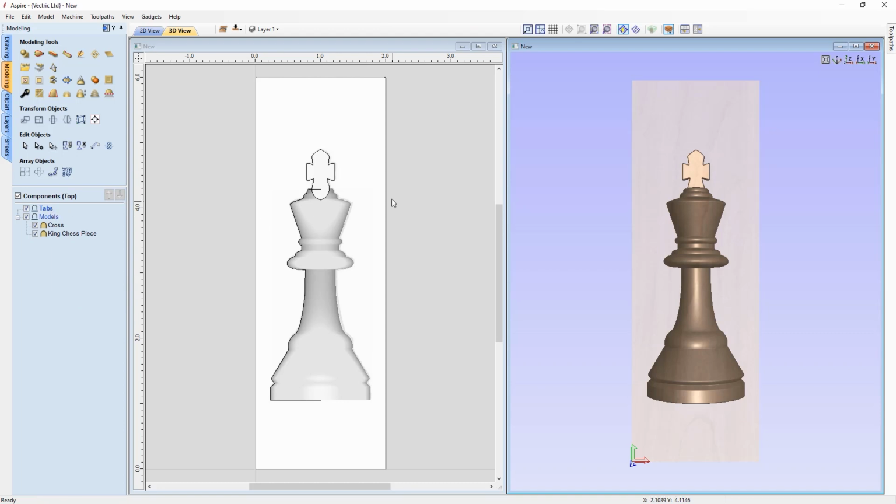And because we want to make sure that our tabs merge in with our finished chess piece here, we're going to right click on that tabs level again, and we're going to change the combine mode to be merge. Now anything that falls on that will end up merging in with our composite model of our chess piece.